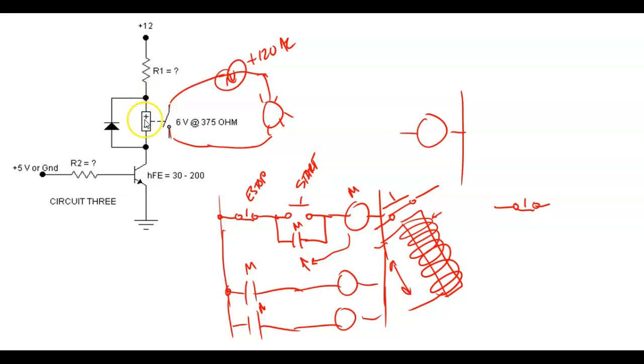So this is a relay. We call this a counter EMF, and I'll show y'all this in a minute. The problem we have with a lot of turns of wire is that it creates a device called an inductor. So if I put AC on this thing it wouldn't work at all. So we have DC relays and AC relays, guys, and they are not interchangeable. If you put an AC relay on a DC circuit, you're going to burn up a bunch of stuff. If you put a DC relay in an AC circuit, you won't create a magnetic field enough to pull it in.